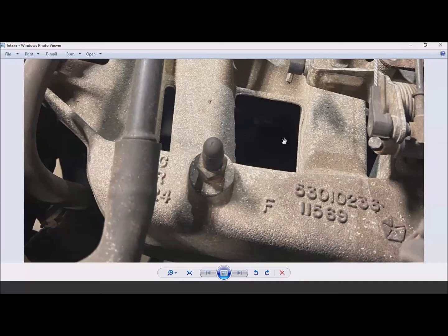And then they hooked it up to a big fancy diagnostic machine. So one of the tests the diagnostic machine did was a cylinder power balance, right? So this is something you should be familiar with now, right? Cylinder power balance, and it indicated that one of the cylinders was weak, and so they told the customer, "You need an engine. You've got a bad cylinder." So this is not the kind of work they did at Auto-Tune. Auto-Tune was just a tune-up shop. So they handed him the fancy computer printout, and in he came.